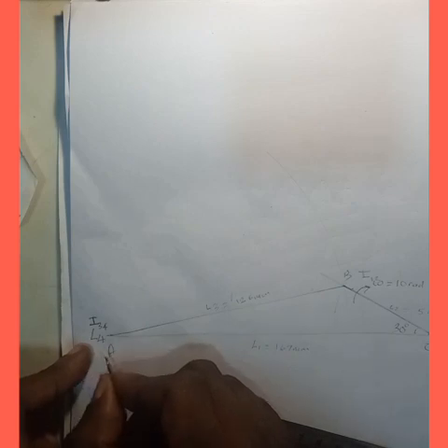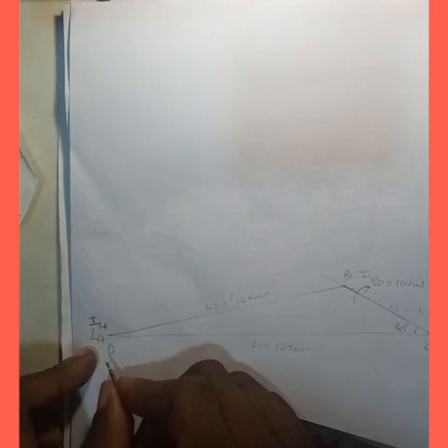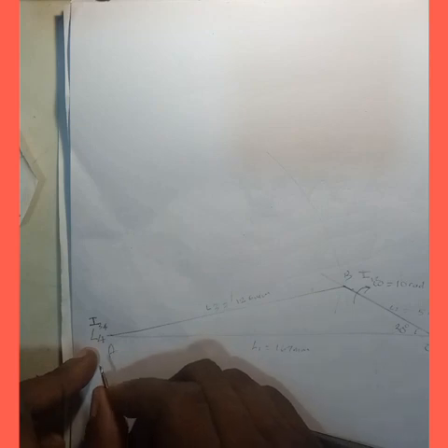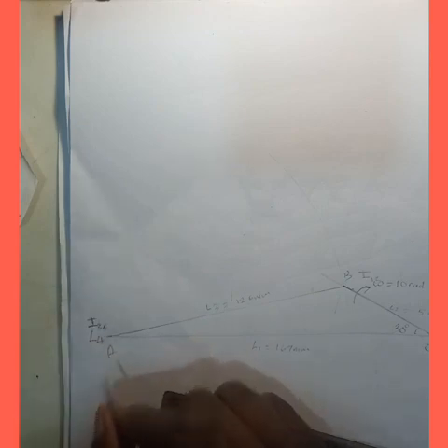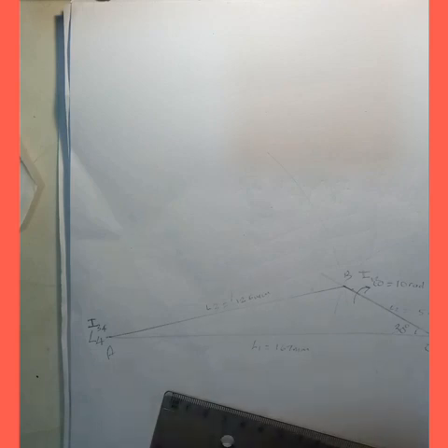Now we also have between link 1 and link 4, because this is link 1, this is your link 4. Link 4 is for the slider. So we're also going to have another instantaneous center there. But now that this is a slider, the instantaneous center is going to be located at I14 infinity. So anytime you have a slider, automatically you know that your instantaneous center is going to be located at I14 infinity.